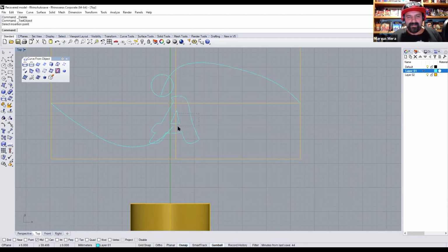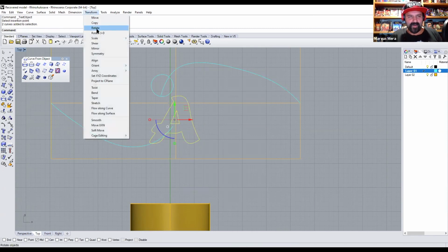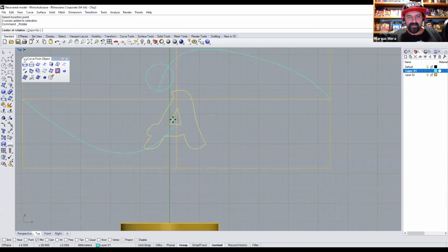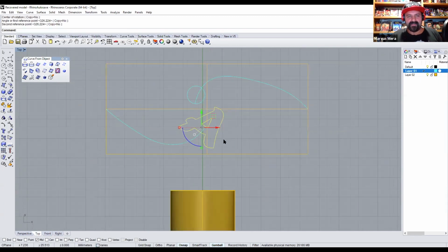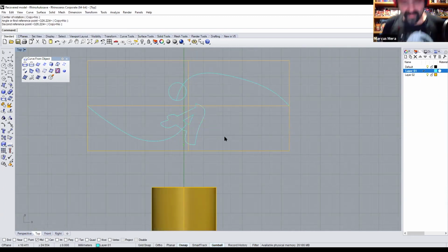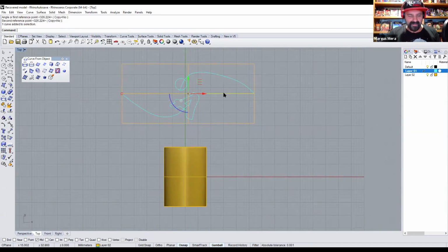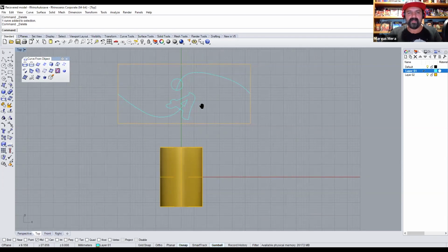Left click, let me rotate again. Transform, rotate, find the pivot point with a left click, drag out, left click, rotate. Much better. All right, that's why I got paid the big bucks. Anyway, so I'm going to delete the references by selecting them, and I have a shortcut Control X for delete, or you can hit the delete button.